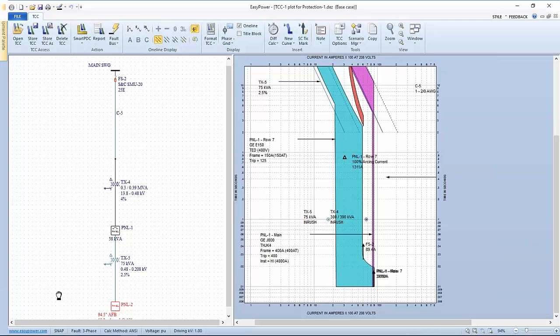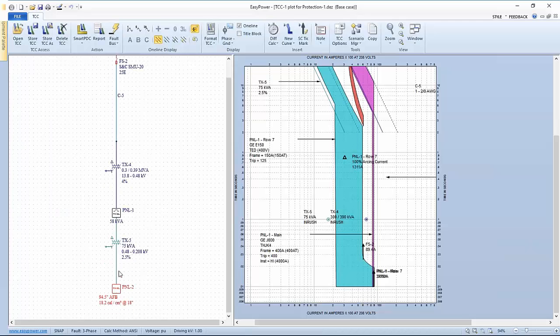The question is, is it real? Well, 5,000 amps, we look at where the tripping point is going to be. So this particular breaker won't clear, it looks like, for 7 seconds. So the answer is, yeah, this could be a problem if we've got that much current faulting or arcing for an extended period of time.